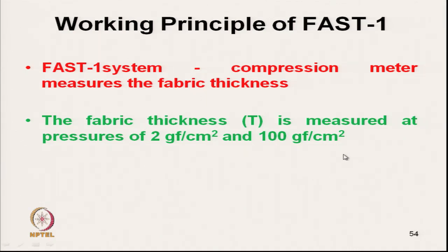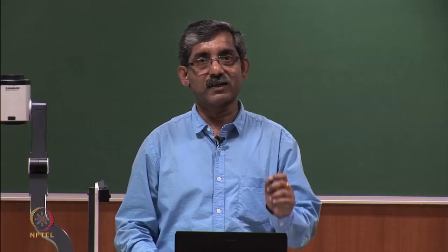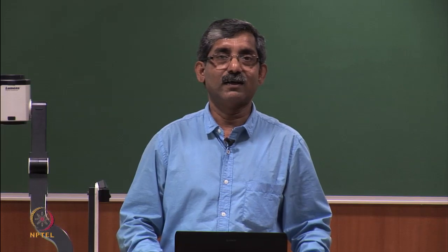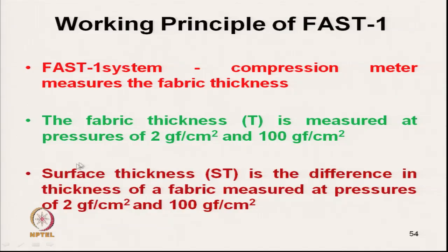So, at 2 pressures we measure the thicknesses, and the surface thickness ST is the difference in thickness of the fabric measured at pressures of 2 gram force per centimeter square and 100 gram force per centimeter square.